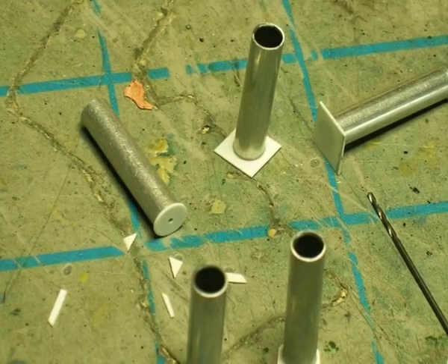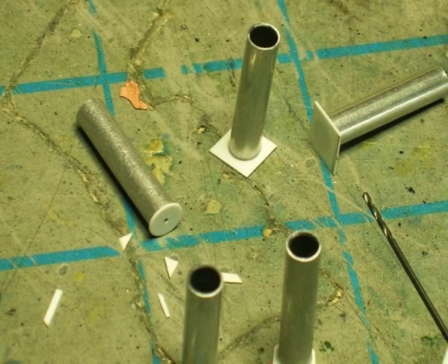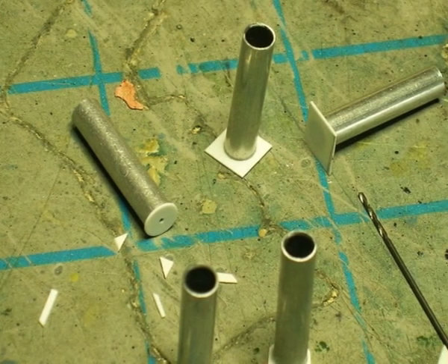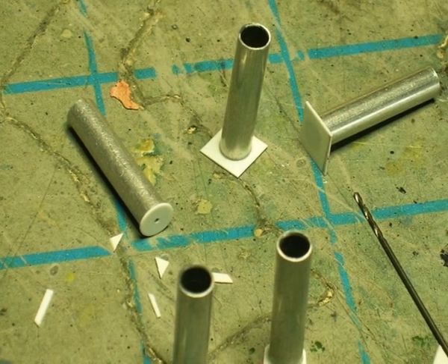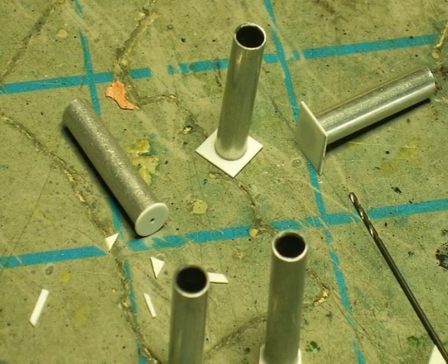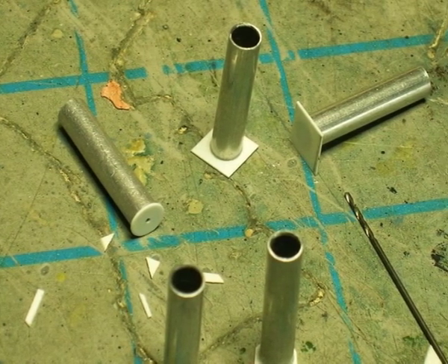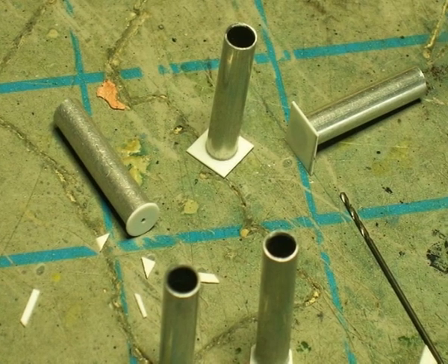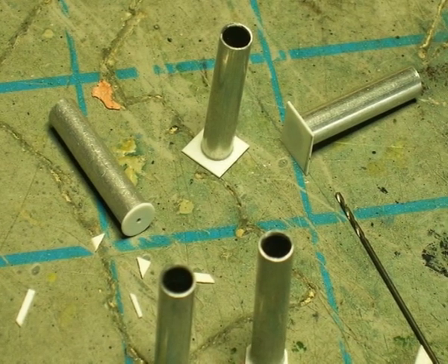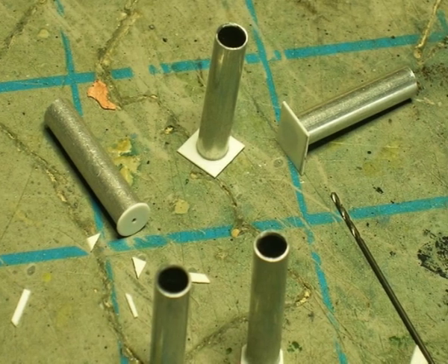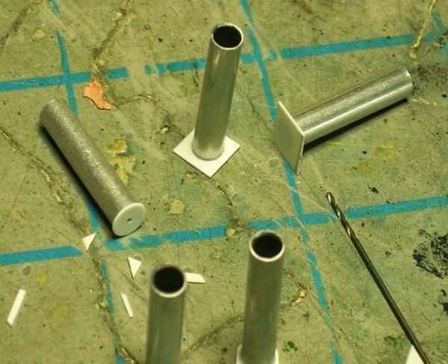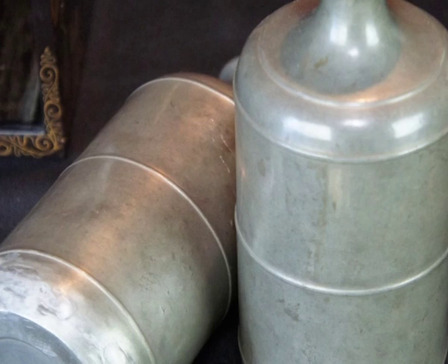Number 2: cross scoring. These are a very potent source of trouble where these transverse scratches intersect extrusion lines. Little sore spots of broken metal are formed which act as nuclei of corrosion on unlacquered metal, and which give big areas of unsupported film in the case of lacquered containers.